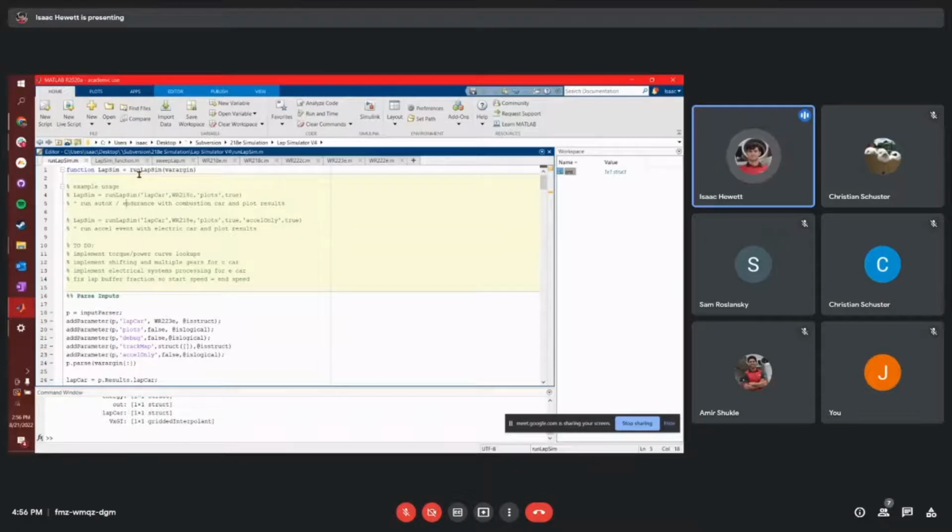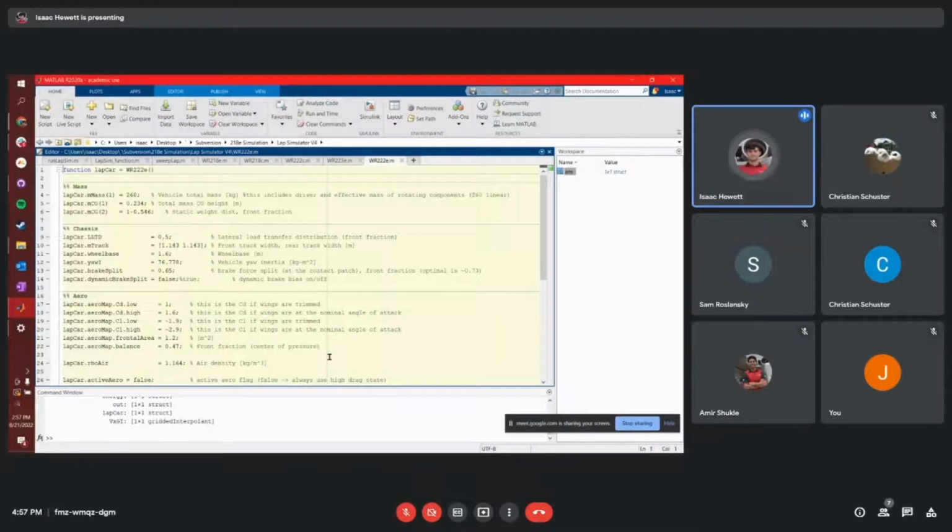Now before we jump into what I think is the more helpful function, which is sweep lap, I want to break down the vehicle model. A vehicle model is what's being run. Effectively, it's supposed to characterize your vehicle in terms of what's being considered within the simulation. And this is where you can update a vehicle model or sweep with these parameters, for example if I want to see the effect of vehicle drag on lap time.